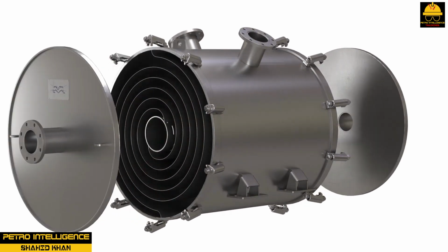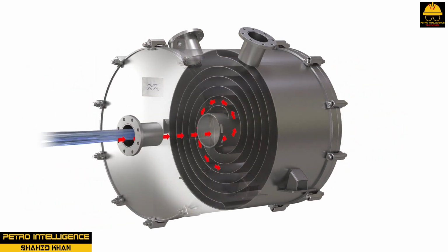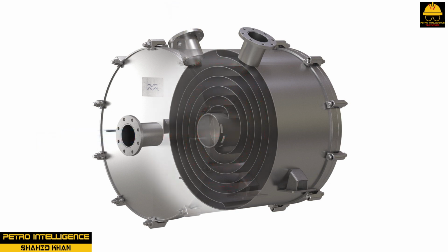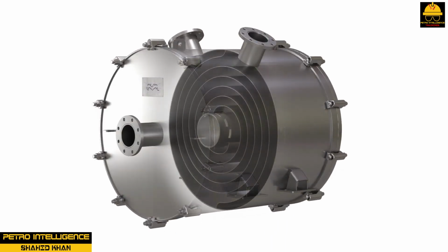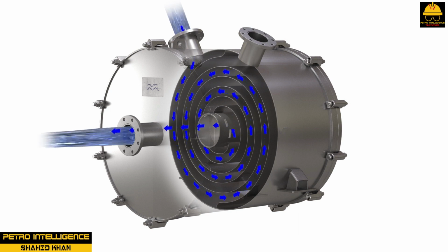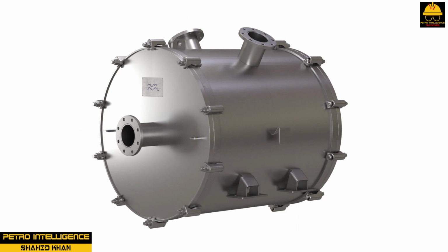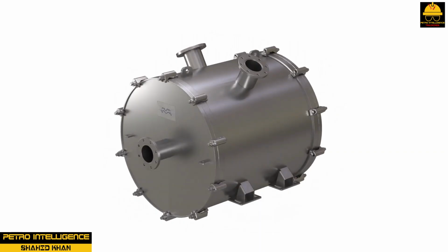Fluid flow into the exchanger is designed for full counterflow operation. The horizontal axial installation provides excellent self-cleaning of suspended solids. Type 2 spiral heat exchangers are designed for use as condensers, gas coolers, heaters, and reboilers. The vertical installation makes it an excellent choice for combining high liquid velocity and low pressure drop on the vapor mixture side. Type 2 spirals can be used in liquid-liquid systems where high flow rates on one side are offset by low flow rates on the other.